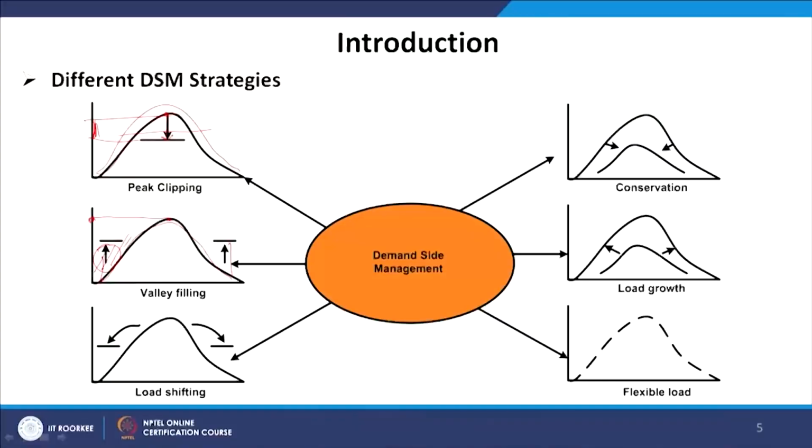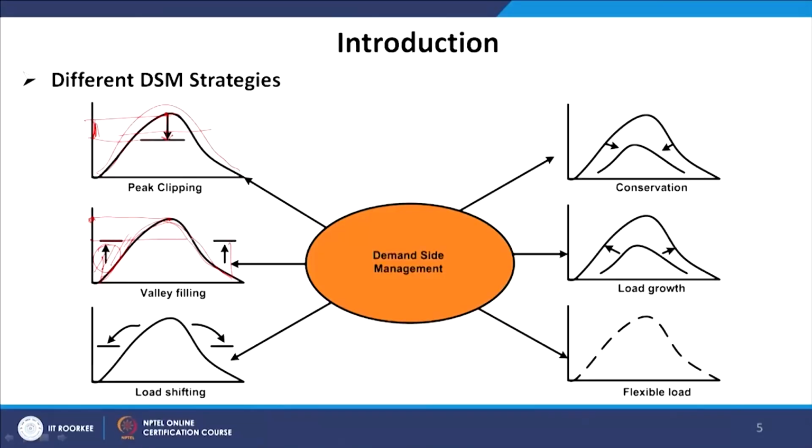After all, the area of cross section, or the energy for a given utility, has to be the same even though the time of operation changes. The area of cross section of this characteristic is the same as that of my original load curve, and to do this the area under this portion is distributed, one portion to this valley and the other portion to this valley.